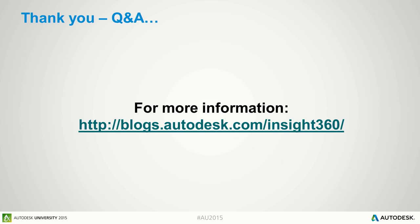You mentioned clouds. Is the insolation level based purely on astronomy, or is it taking into account low hills and valleys in cloud? It's based on the Perez calculation, a regression model that's generally used by most solar analysis tools, NREL and PVWatts and so on. It uses the direct normal and diffuse horizontal radiation and figures out the solar intensity coming from different areas of the sky: the circumsolar, the solar disk, the horizon, et cetera. So it knows where it's coming from.